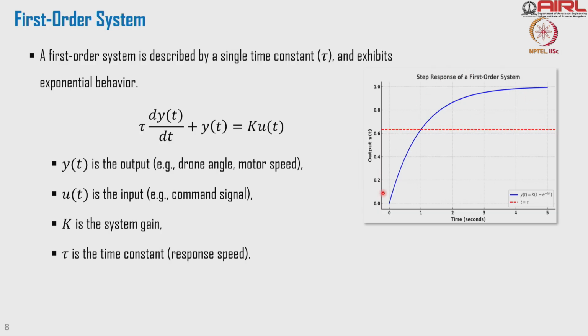The blue line shows how the system responds, and how much time it takes to go from 1000 to 1100. It takes 4 seconds. Is that acceptable for us? That's what we will be analyzing, and it tells you whether the requirement is satisfied or not. If not, we need to design a controller such that this response can be modified. We will talk about controller design in a later part of the lecture.